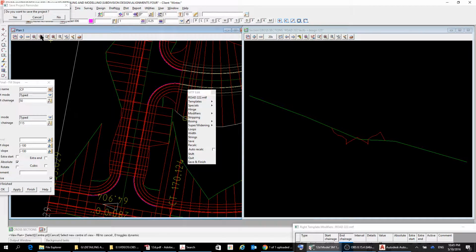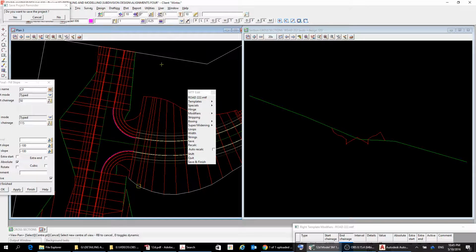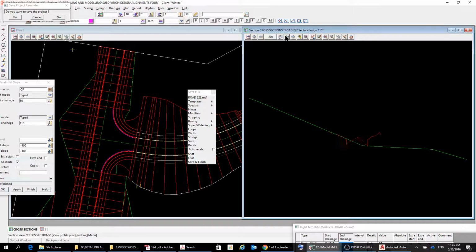And if we come back down the road here, just past the intersection, we can see that once it gets here, this material is draining down to that road as well. So that should resolve itself. It shouldn't create any ponding in here.